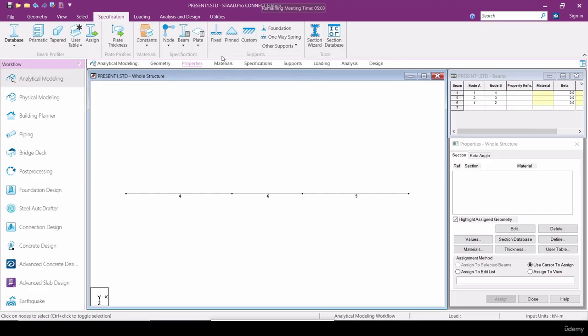Generally, any PEB structural design engineer tries to design a structure with pinned base only. Because the foundation would be smaller and you can do tapering for a column. Why can you do tapering for a column with a pinned base? Suppose the structure has a pinned base, what is the moment at the base? Since it is a pinned base, a pin will not have any moment, right? Moment will be zero at the pinned base.